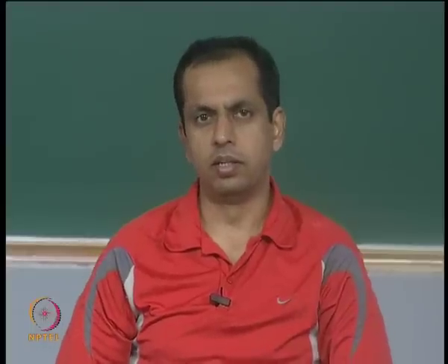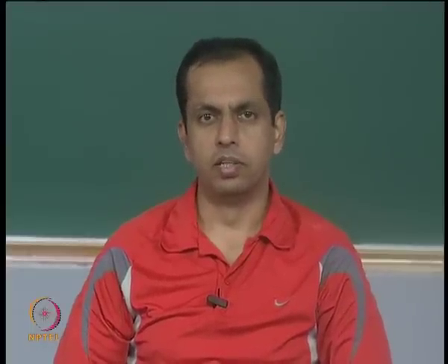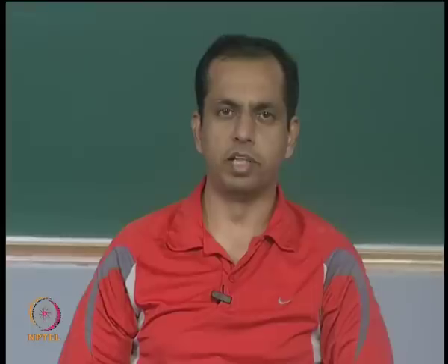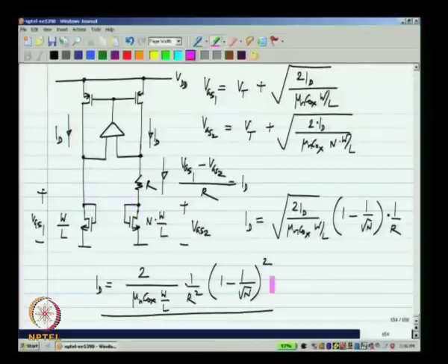It turns out that exactly the same circuit that works to establish a constant GM in bipolar transistors also works for MOS transistors. Okay. Now, it is assumed that the MOS transistors are operated in strong inversion saturation. Okay. Now, if the MOS transistors are in a weak inversion, that is subthreshold region, then the MOS transistor behaves the same as bipolar transistor. It will have an exponential IV relationship and then also it works. Okay. So, this circuit also works for MOS transistors, but there is a slight problem with this.